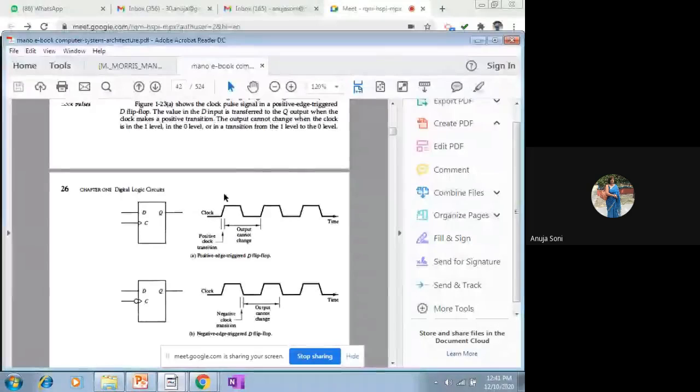So again, I'm repeating, in the case of flip flop, with the help of the characteristic table, what we are doing is observing the behavior of the output variable generated at the t plus 1th timing signal with respect to the output generated previously at the tth timing signal.